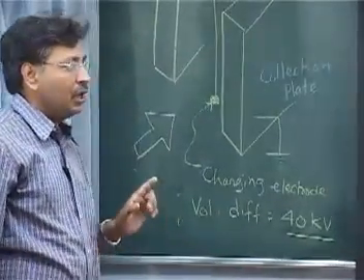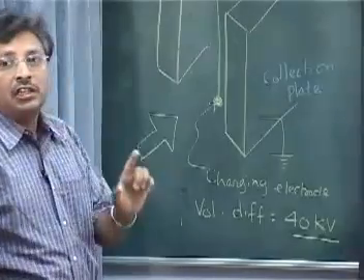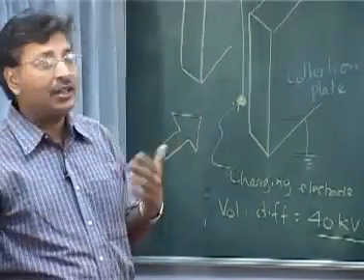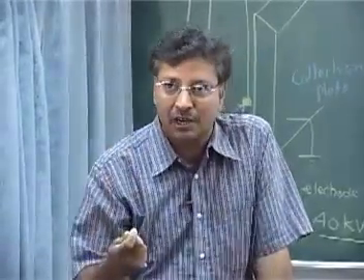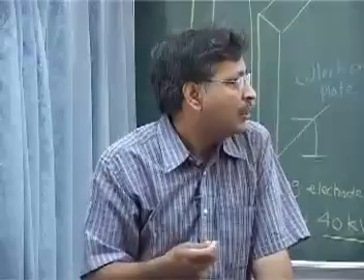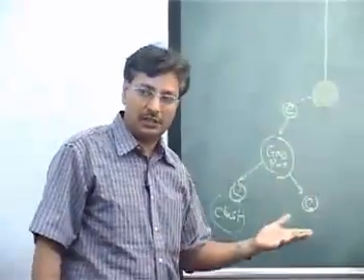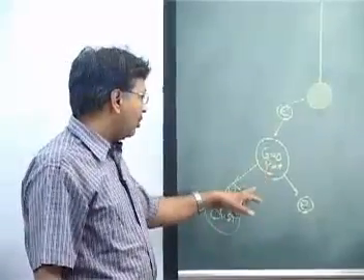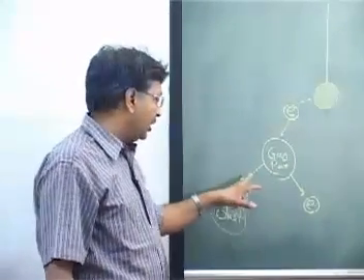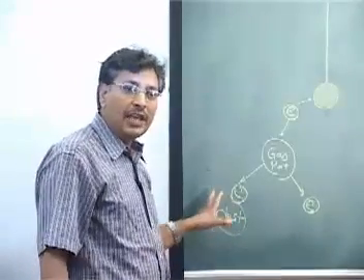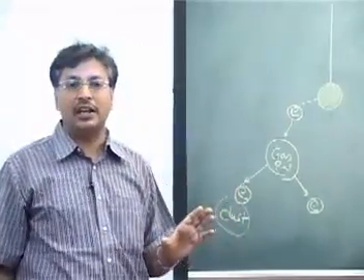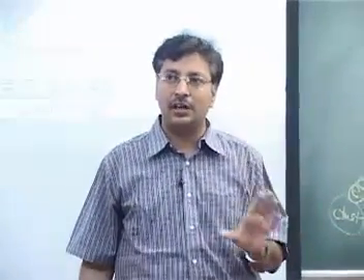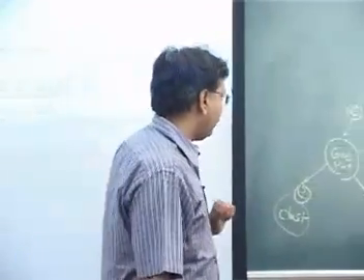So remember that ionization is taking place only for gases, because sometimes people get confused: they hit the solid particles or dust particles and the particles become charged, so where are the electrons coming from? But that's not the case. The thing which is getting charged is the gas, which is generally the air or the flue gas, and then more electrons come out, and these electrons sit onto the dust particles. These dust particles continue to travel because of the charge they are carrying towards the collection plate, and then they go ahead and sit onto the collection plate.